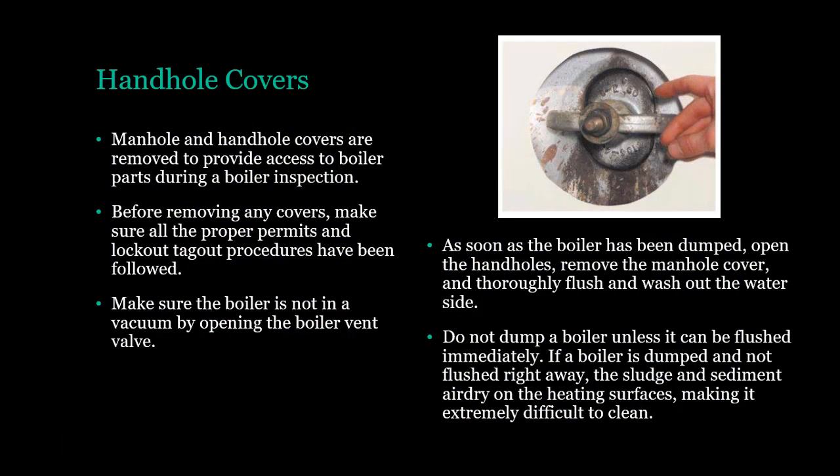Manhole and handhole covers are removed to provide access to boiler parts during a boiler inspection. Before removing any covers, make sure all the proper permits and lockout-tagout procedures have been followed. Make sure the boiler is not in a vacuum by opening the boiler vent valve.